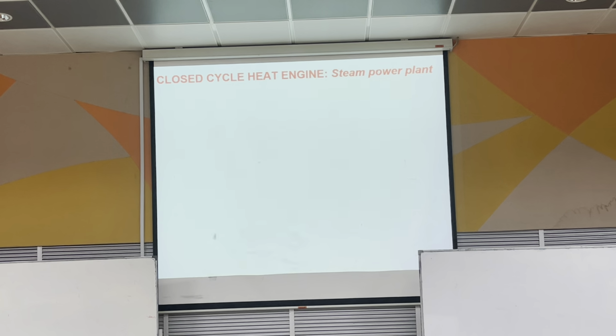So the input here is heat input, but the desired output cannot be simply work out because you are using a certain amount of work in. So you still have some input there. That's why we call it the net work output instead of just work output. So the net work output is work out minus work in.